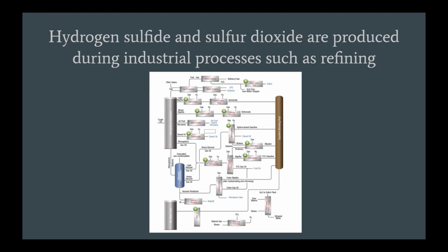A common way of doing this is through hydrotreating, which results in hydrogen sulfide. Other treatments can also be used that result in sulfur dioxide too. But on this chart specifically, the main part where the side product is leaving is the off-gas portion in the top right. This is shown by the hydrogen sulfide entering the Claus sulfur plant, where this hydrogen sulfide was extracted using amine treating.